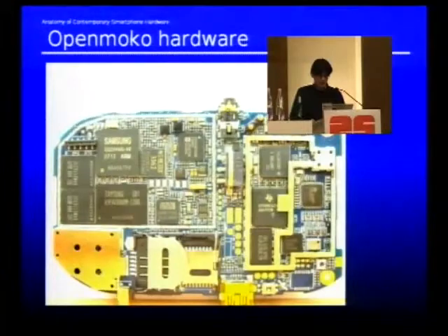And the section which has the frame for the shielding cover over here is the actual GSM modem side. This one is the baseband processor, then we have the DSP over here, some flash and RAM in one package down there, and this is the RFPA, I think, over here. And the section here, which is completely covered, is the GPS unit that is separately shielded because GPS has very sensitive signals. So this is basically how something like this looks.